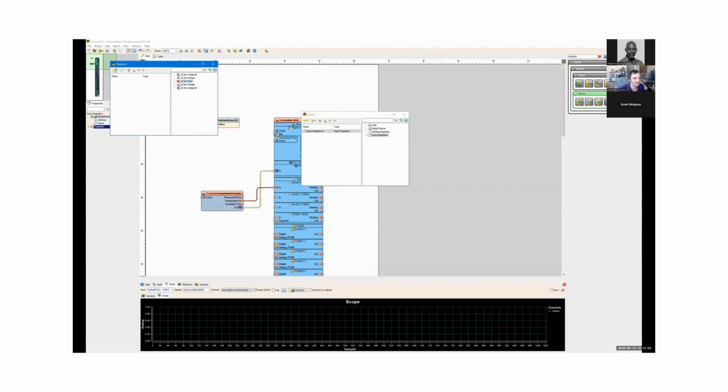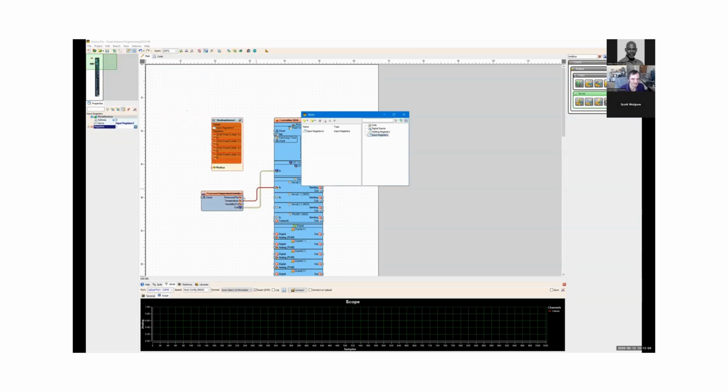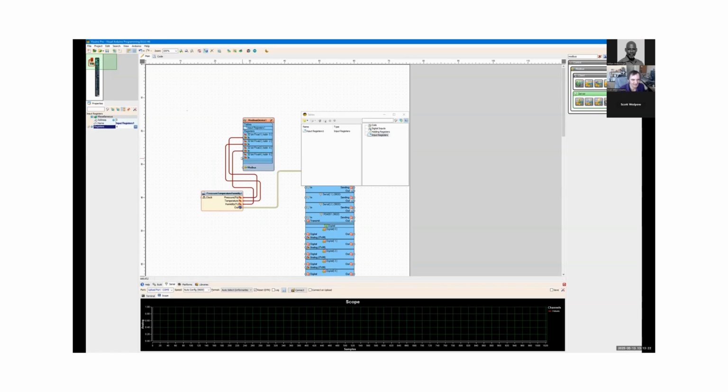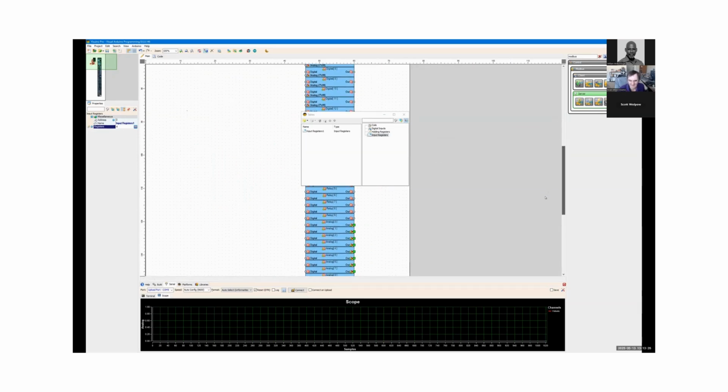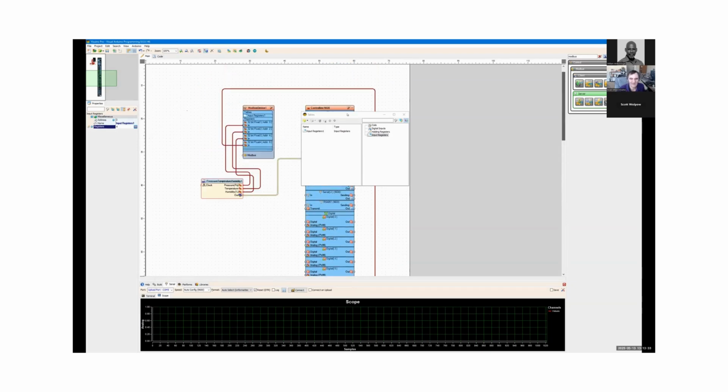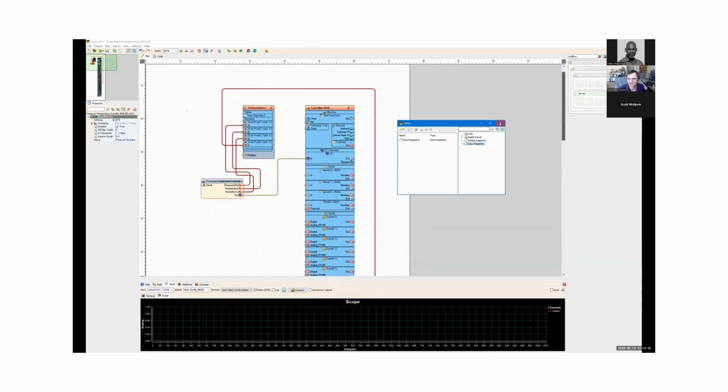And now add 4 of them. So I'm adding 4 analog inputs, and I'll start connecting the different pins with values to the different channels, to the different input registers. And the final one, if I remember correctly, my light sensor is on analog 0, so connected to analog 0. So that's it. We have the data sent to input registers.